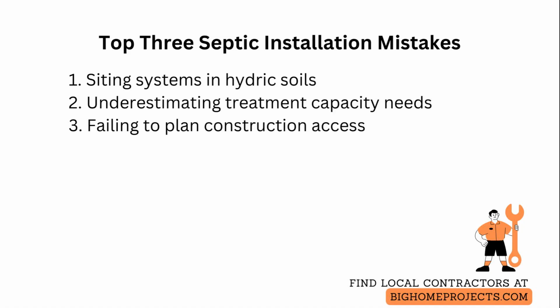A third problem is failing to plan access and construction limits, which causes erosion and trampling. Create a narrow, designated access corridor, install temporary matting, and schedule work during dry seasons with immediate erosion control and post-project native revegetation.